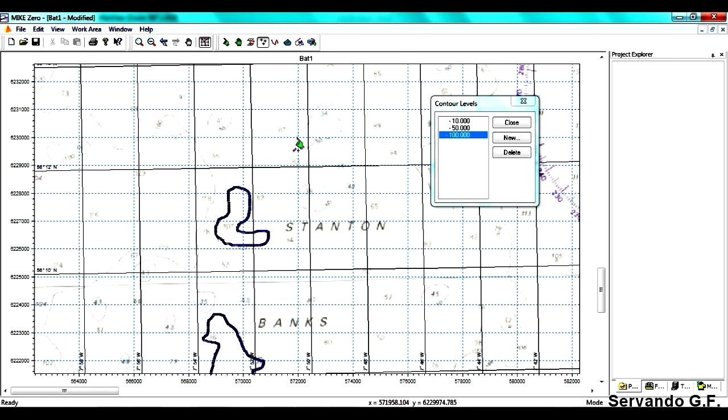The other way to define the bathymetry is this one, Add Points. If you want to save some time, maybe this is going to be a better option. And this is define a limited amount of points that will define your contour line. So as you can see, this is an easier method, and depending on the accuracy that you need, maybe it will be worth it.